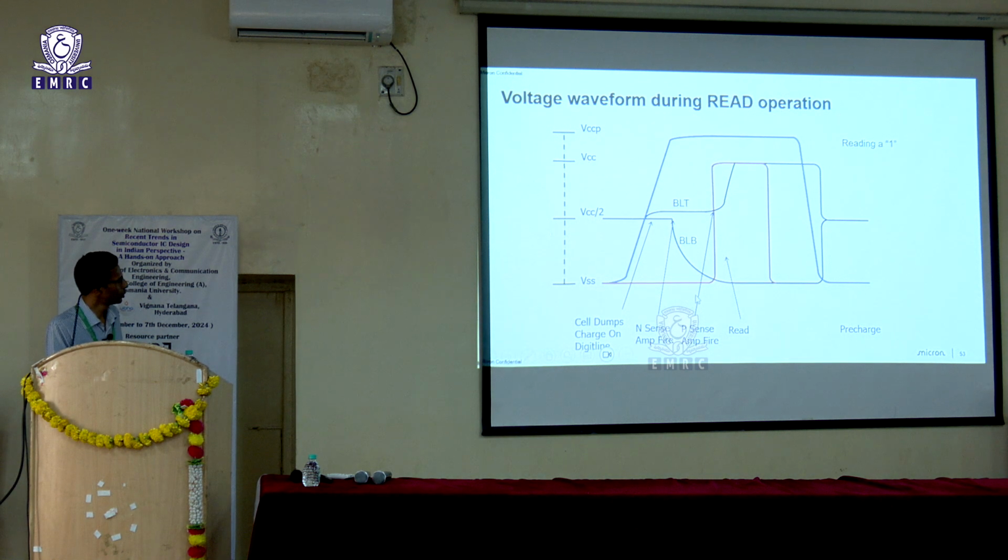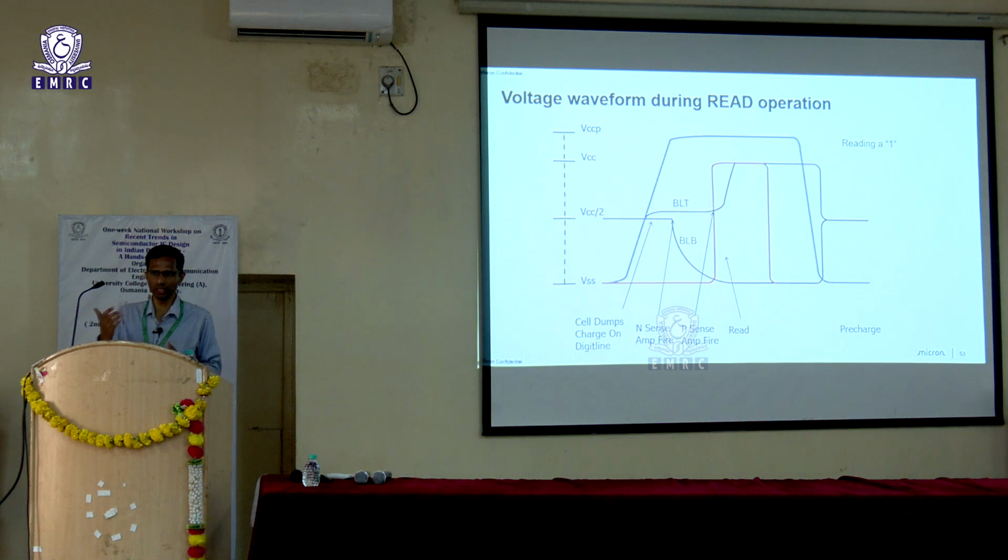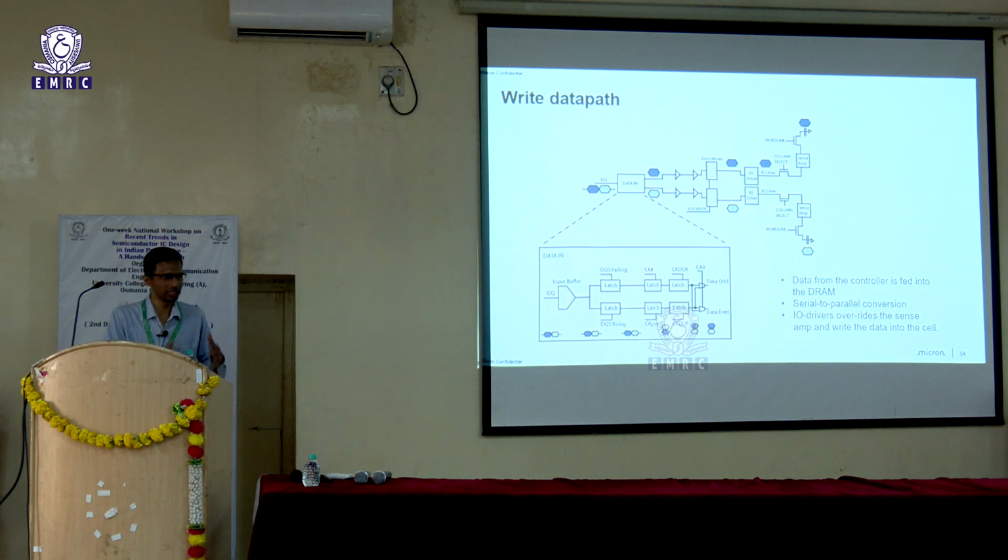and then you come back and turn the PMOS cross couple on as well. That is when the one which is currently residing close to VCC by 2 will go all the way up, and now you have a rail to rail information which will eventually be fed out to the other stages. Same is true for the write path, it is just opposite.